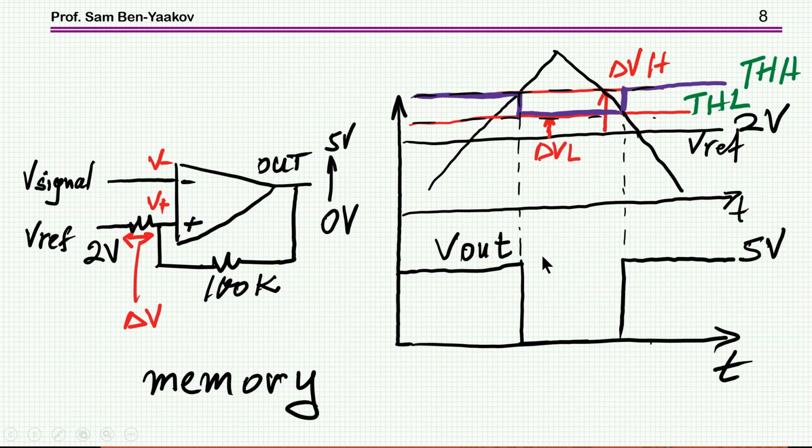And here I'm showing a very basic concept of how it will work in the case of an operational amplifier or a comparator. So we have a signal coming in here, and here is a reference. Now, for the amplifier or comparator, what is important is the difference between the input terminals of the device. So as the signal is changing and the output responds, we are going to feed back a signal that will actually change the voltage across this resistor, thereby creating two thresholds. Because if the output is high, we have a positive voltage here, so we have to move the signal to this signal here.